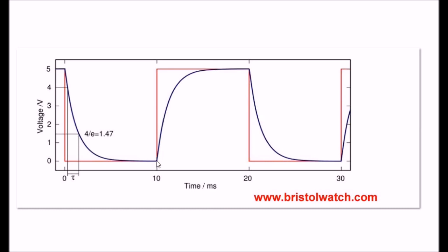The more input capacitance you've got, the longer and more drawn out this charge curve is going to be. When you go to zero and switch on that lower transistor, it's also going to have some kind of resistance, and the capacitors that were charged up when it went high are going to discharge, but not in a linear fashion.